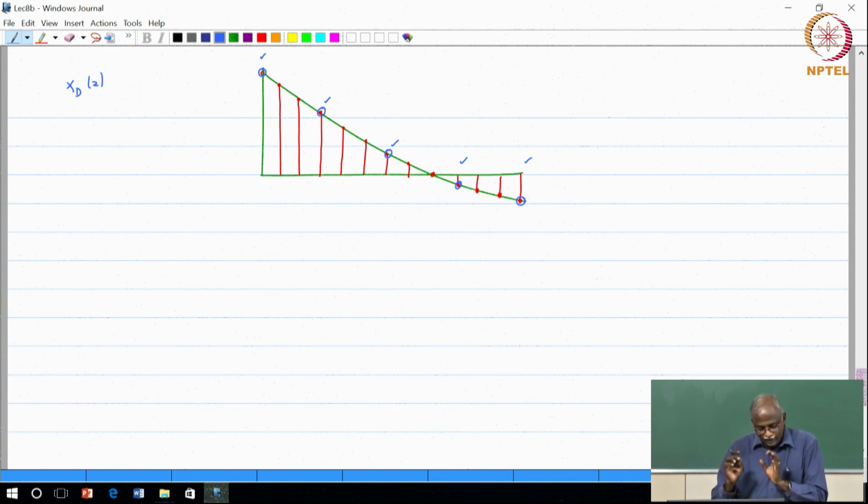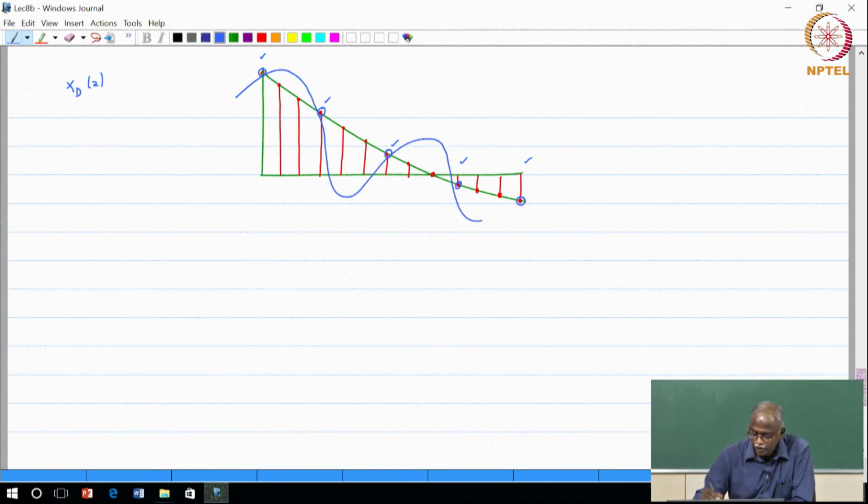Okay. Now, here is the example and its illustration. Just as a case study, if I had a continuous time signal given by this blue graph and it had been sampled, I would have gotten the same samples as if I had the green line and sampled it at this rate. Now, when I am given only the samples and asked to reconstruct, what I am most likely to reconstruct is something that looks like the green line, because I do not have enough information to reconstruct the blue line.